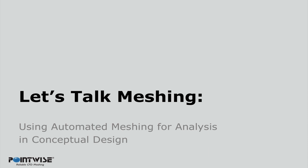Today, we're going to explore an approach that may help engineers incorporate high-fidelity, physics-based, multidisciplinary analysis such as computational fluid dynamics or finite element analysis into their workflows during the conceptual design phase of aircraft development. This approach couples OpenVSP's easy-to-use parametric aircraft geometry tool with Pointwise's automated meshing capabilities to more readily automate the process of obtaining a viscous anisotropic mesh from users' models created in OpenVSP.